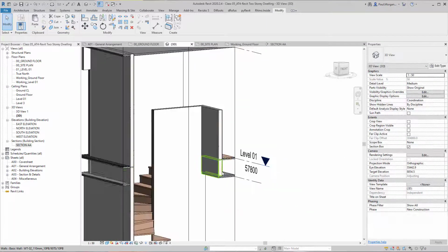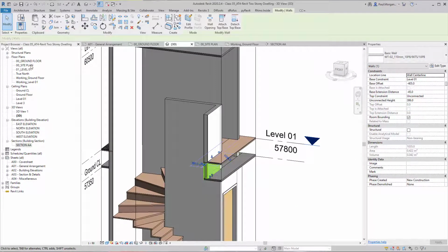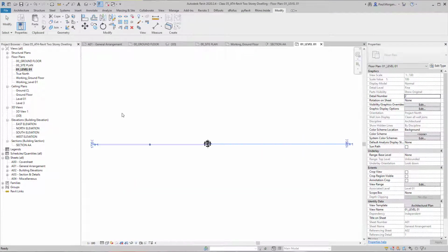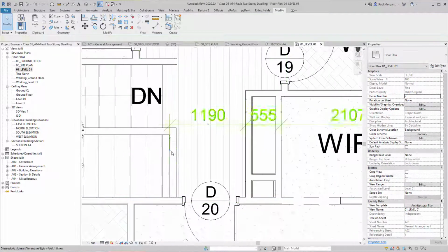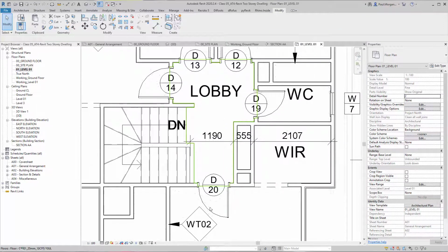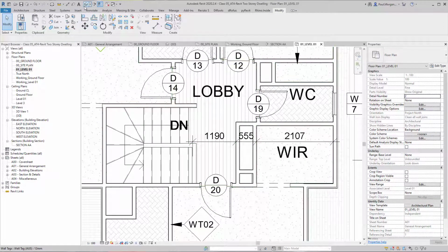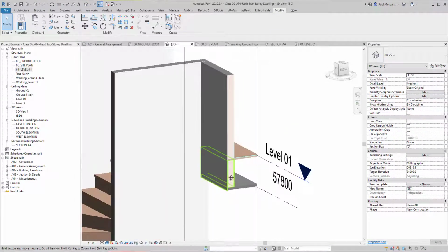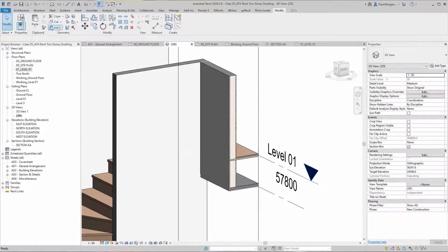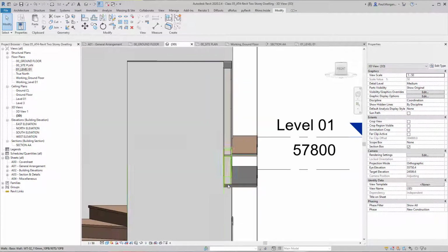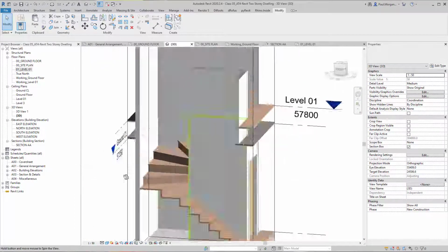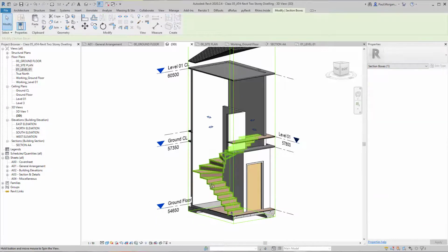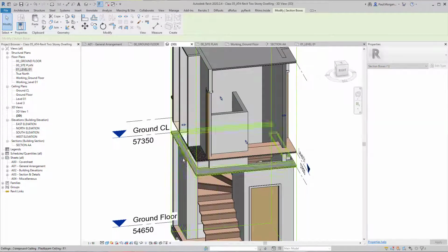There we go. I just want to make sure that in my level 1, how far is that wall drawn? Yeah, that's only that. Yeah, that's perfect. That looks good. Go back to here, and then go Join 1, 2, and now that plasterboard's missing, and that construction detail is accurate.